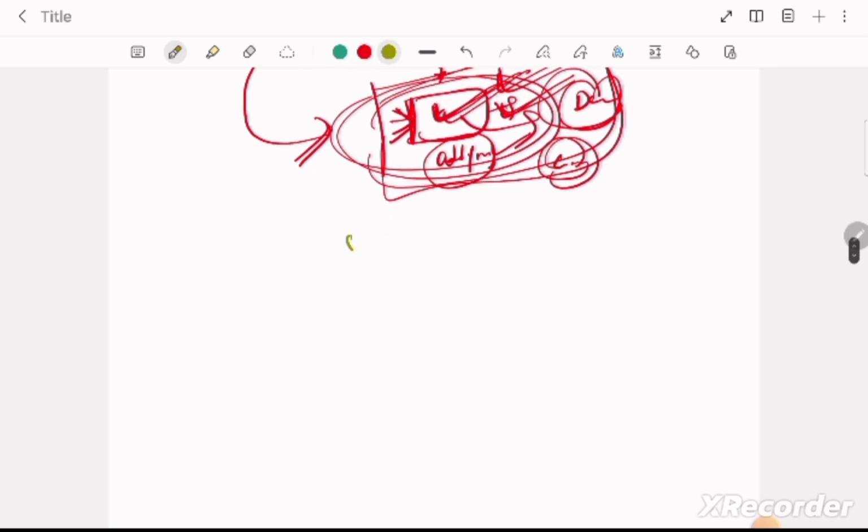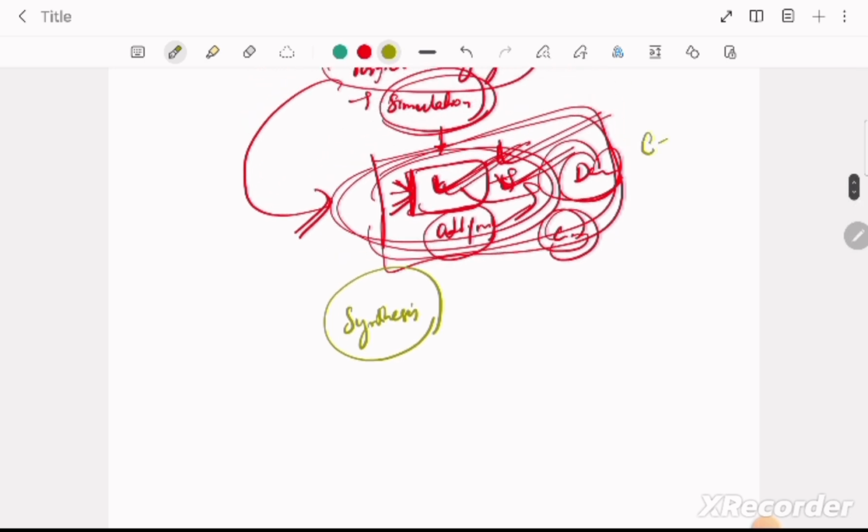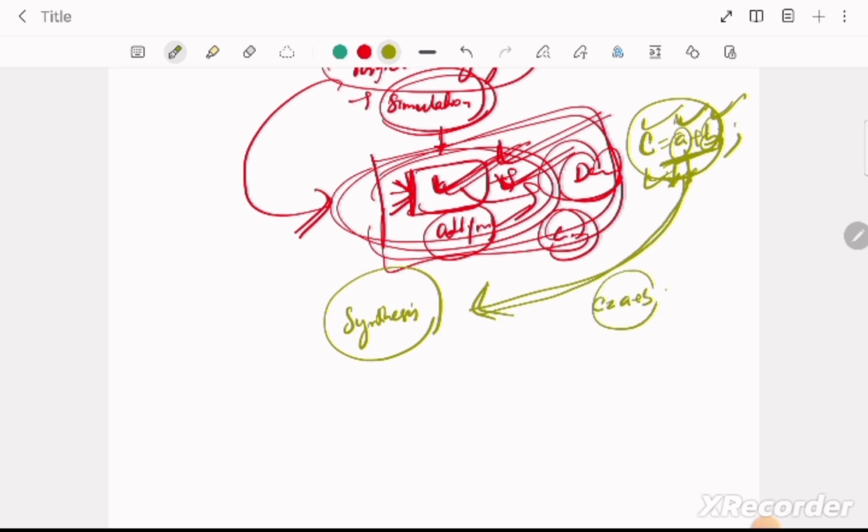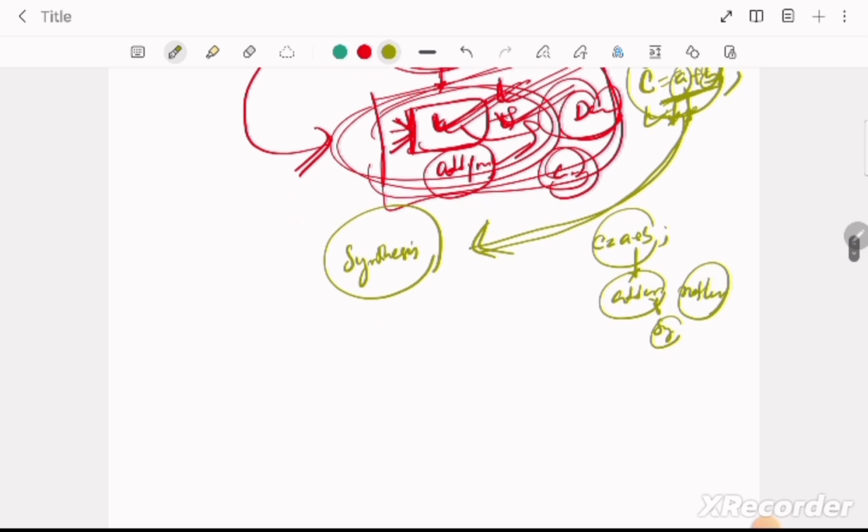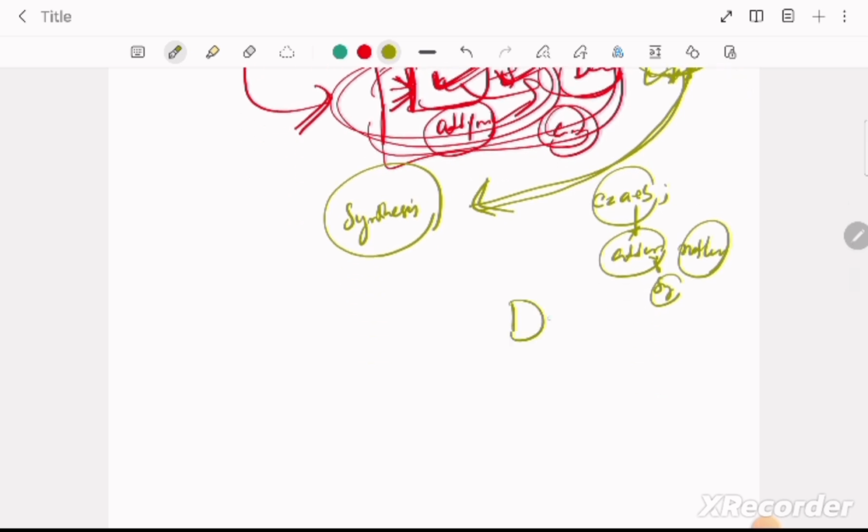And also Verilog is a synthesis language. So what do we mean by synthesis? Let us suppose we write C is equal to A plus B. We are describing the adder operation where A is one input, B is one input, and the output will be in C. By this we can simulate whether we are able to achieve this with respect to some timing constraint, meaning the functionality should be validated here. But when we go for synthesis, we check how this particular C is equal to A plus B, what type of adder will be synthesized. When we get a netlist, it is a type of structure where we have this design in terms of the actual gates.